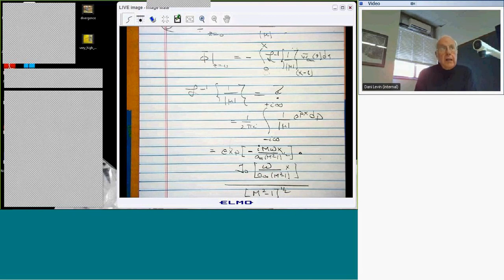And that's been known more or less for a while, although I'm not sure it ever was rigorously shown until relatively recently. But the way to show that is to go back to the transform plane and take the limit as the Mach number becomes large before you do the inversion. And then it's obvious that you get piston theory. And the same thing is true if the frequency is very high, but that was only done relatively recently.